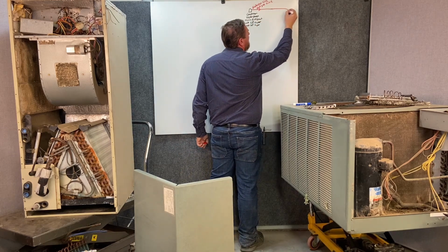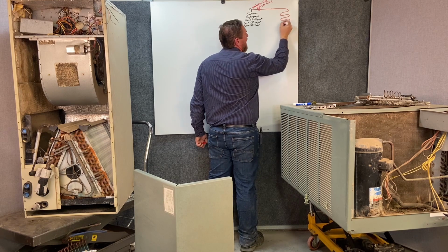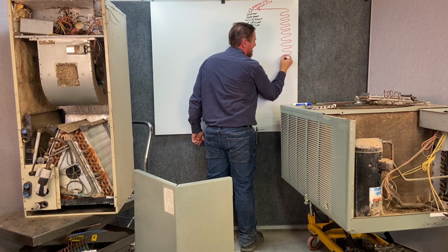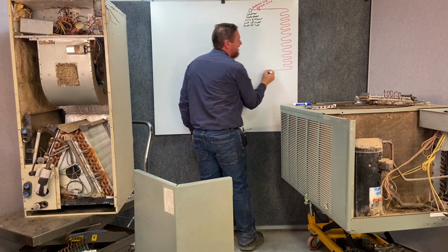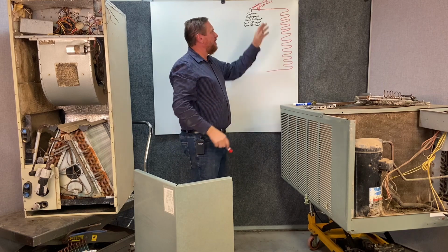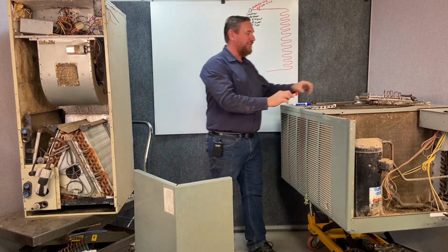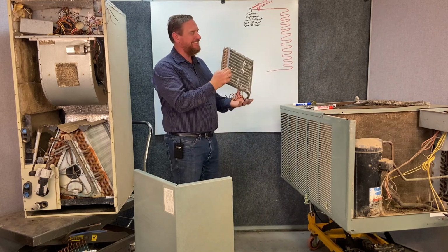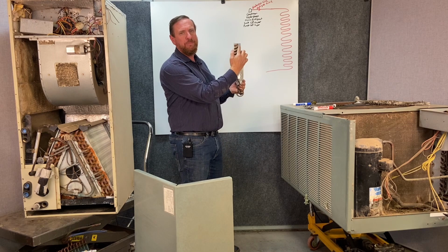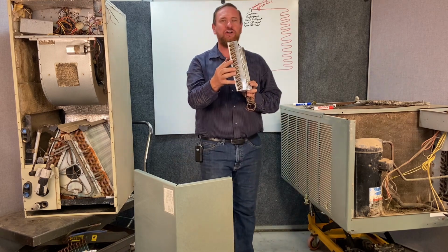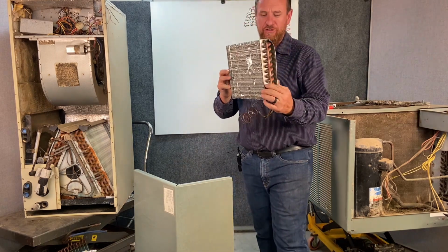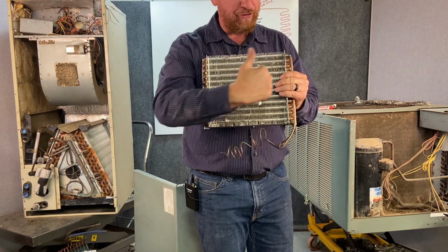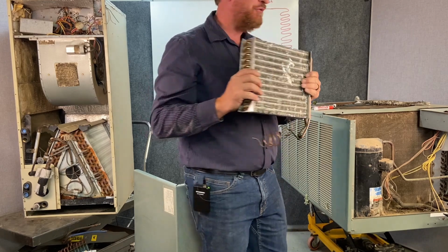Next, what I'm going to do is run my marker back and forth, back and forth, back and forth. Now, I've done this many times. Many students say that doesn't look like the unit at all, and I get that. My compressor doesn't look like a compressor at all. This doesn't look like a condensing unit at all, but the idea is you see these little tubes going back and forth on our coil. This is a small condensing coil out of a refrigeration system. I'm representing the refrigerant going back and forth through this condensing coil.